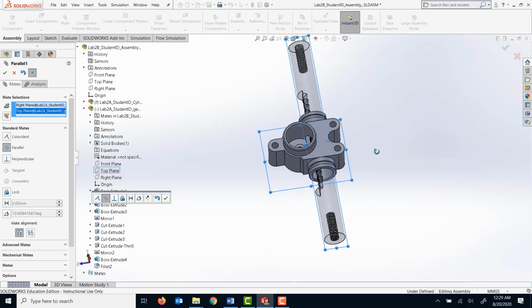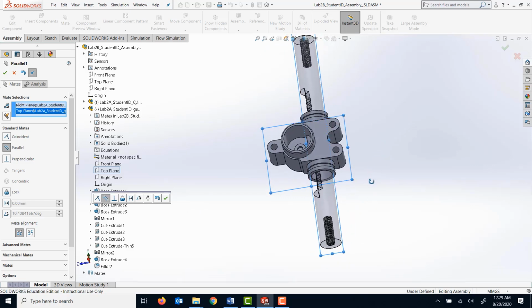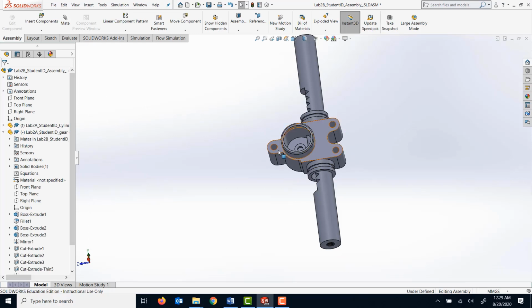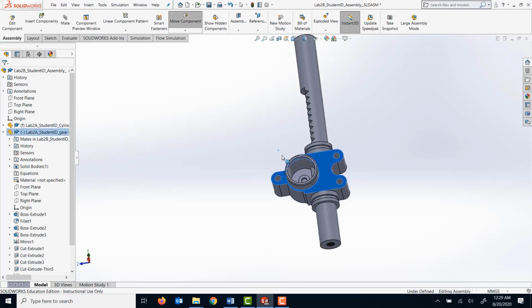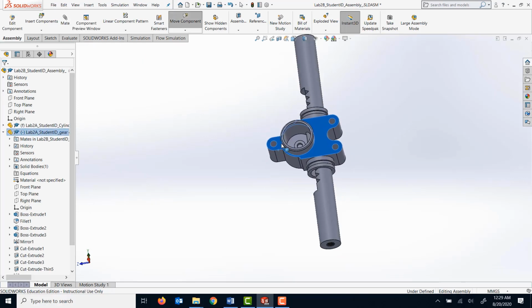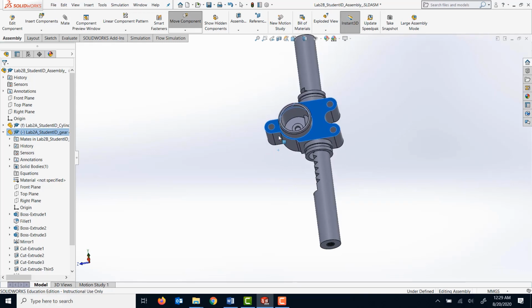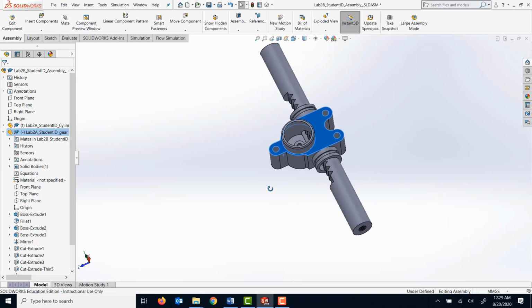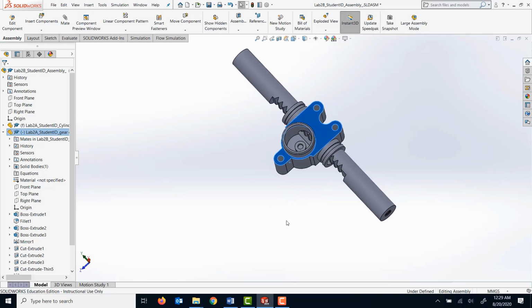Just make sure that you add the appropriate relationship within your assembly. So I'm simply gonna click OK to that. So now I'm gonna exit the mate dialog, and I'm basically gonna test it out. Now I see this cover only slides along the rack cylinder.